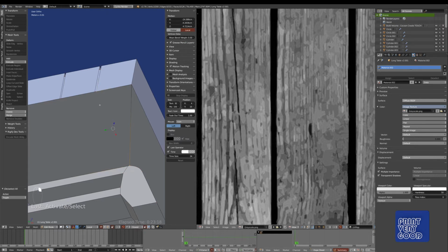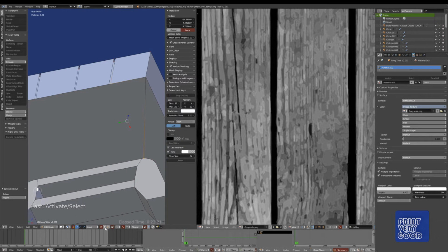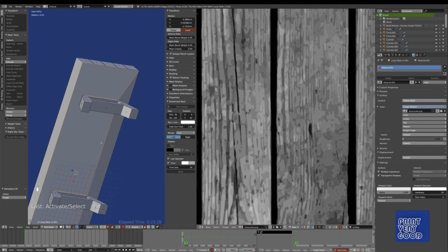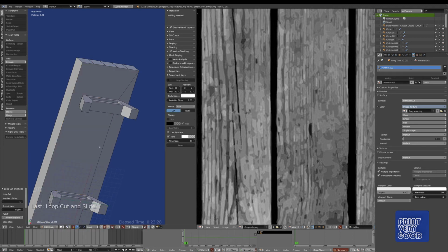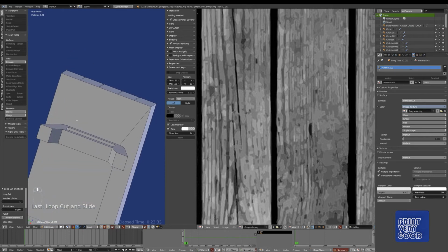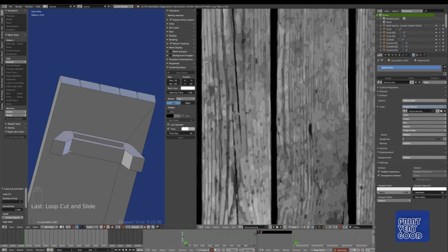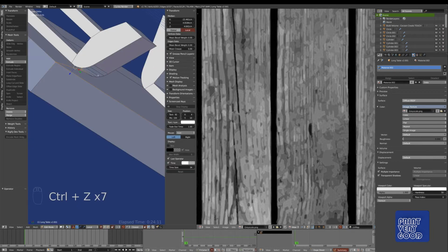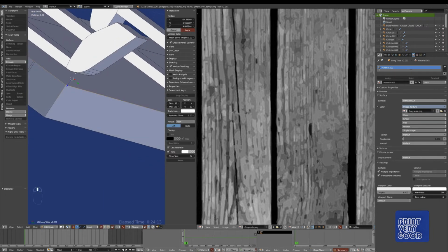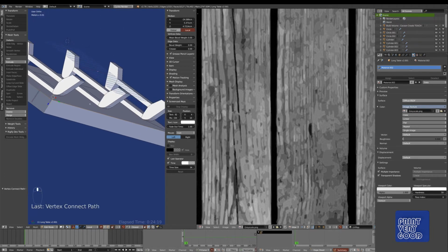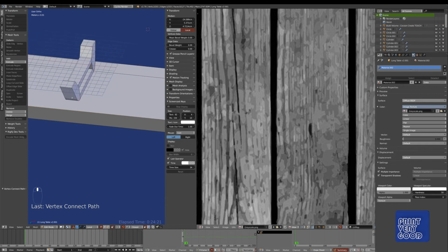And you can see that J is not working because that piece of geometry there didn't have the vertices on that bottom edge that I had created on the other side. When you have an edge and you press W and subdivide, it creates vertices for that edge in both directions basically. So I'll go through and just add this geometry into the base to correct this issue, and we'll come back shortly.